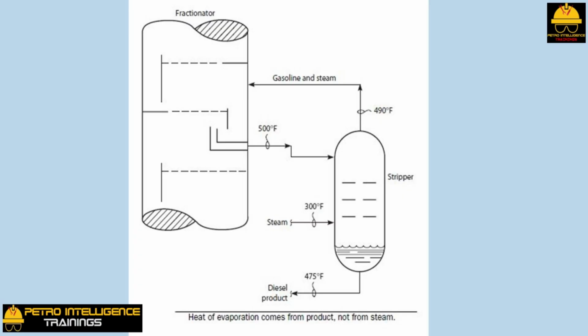Stripper efficiency. Many side-stream steam strippers of the type shown in picture do not work very well. Operating personnel report that the stripping steam is not effective in removing undesirable lighter components from the stripper feed. Why could this be so? One of the main reasons for this sort of poor stripping efficiency is subcooled liquid feed to the stripper.